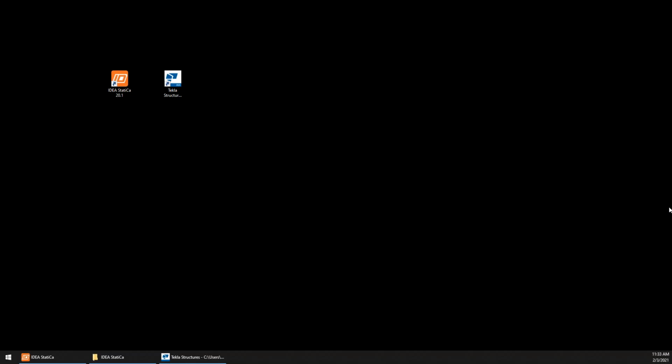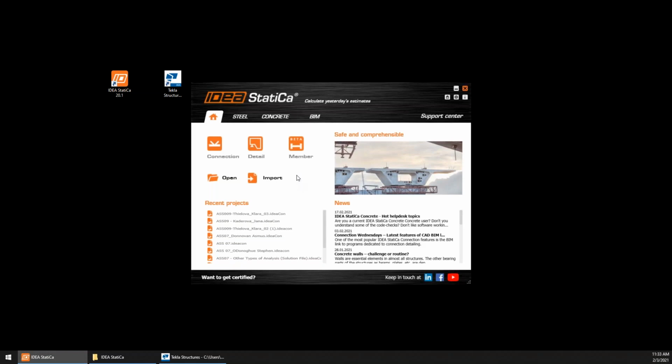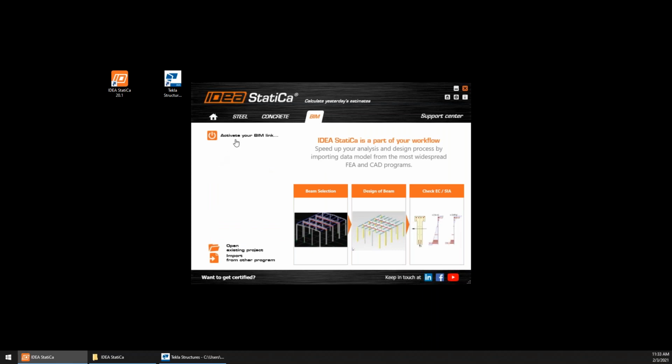And now in my part of the presentation, I will show you how to integrate the BIMlink plugin into your FEA or CAD application. And in the second part, we'll take a look at how to solve the situation when something goes wrong during this installation. So at first, I'll show you how to perform integration in a standard way. So we can start via the initial IDEA launch screen. It's the first screen you can see after launching IDEA StatiCa. And here in the fourth tab named BIM, you can find this button, Activate your BIMlink.